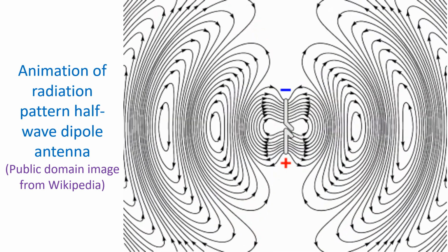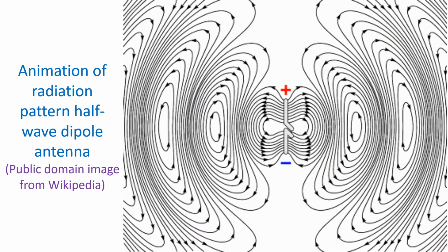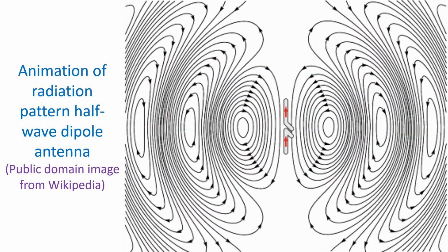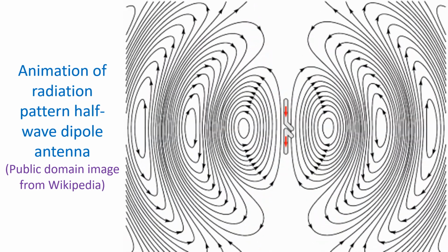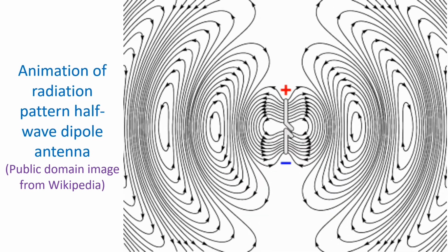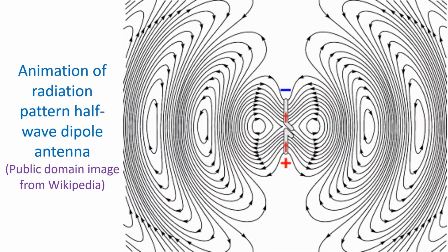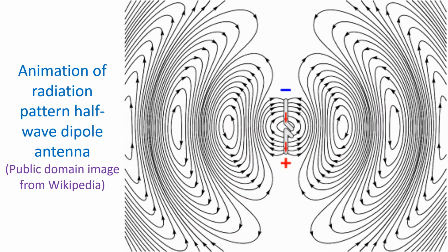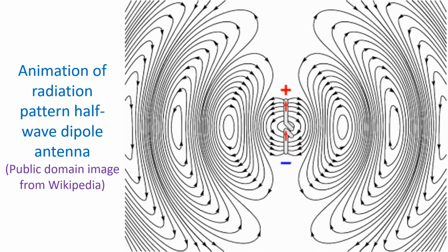Dipole antenna has a directivity along its broadside and hence has a gain of 2.15 dBi with respect to the isotropic antenna. Hence, gain expressed as dBd of any antenna will be lower than that expressed as dBi by 2.15.